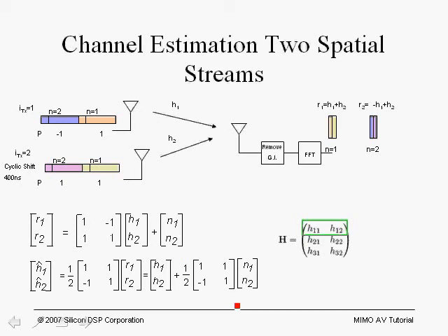So that's one of the advantages of using the orthogonal method in order to train for the H matrix entries, is the fact that the orthogonal matrix that is used is actually unitary, and in this case it's real, so it's actually an orthogonal matrix. Then the noise is not enhanced. So this is a big benefit of this technique.